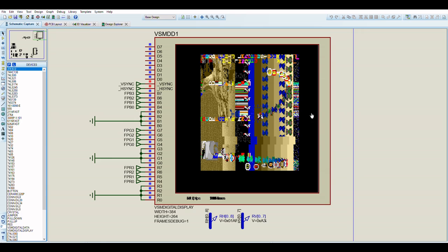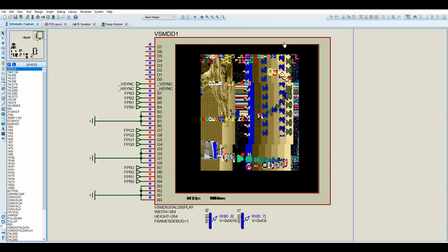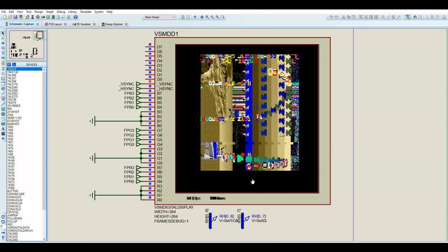We can see that there is a raster split going on, in that the bottom part of the tile screen actually scrolls at different rates compared to the top. And actually I can update the scroll registers for the tile screen at any point during the screen, so I can have 3, 4, 8 horizontally and vertically proportioned screens. If I use precise horizontal pixel timing, like a copper list, then I can have horizontally and vertically split screens in terms of screen scroll.